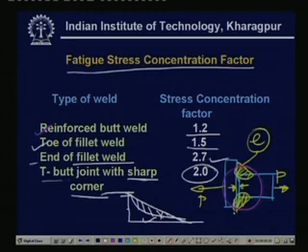Now, let us come to the conclusions. We have learned the different kinds of welded joints and how to design them. Designing is very difficult, and we use the thumb rule that it is only at the throat where the stress is maximum, and we design the welding considering only the throat cross sectional area. There is various literature available. If you have a chance to look at some of the textbooks, you will find many such design problems given; you solve them. Okay. So, this is as far as the welding joint is concerned, and I end here today. Thank you very much.